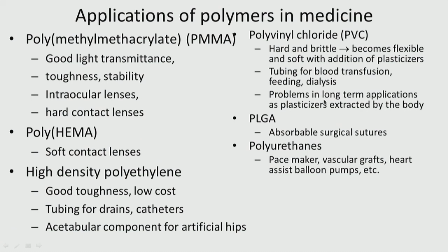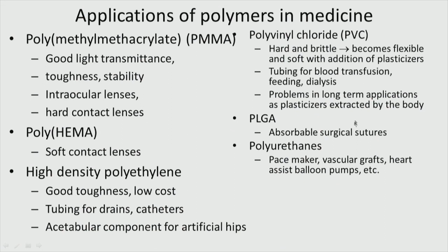One big problem is long duration. Some of the plasticizers like phthalates, used to make it flexible, may start leaching out into the body fluid, which may have an adverse reaction with the cells and may cause toxicity. That is one big problem with PVC. For long duration it is not very advisable, because the added plasticizers could create problems. So it is good for short duration applications like dialysis and blood transfusion, which may last a few hours.